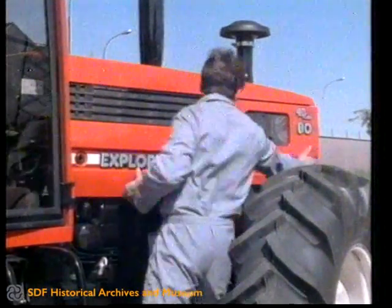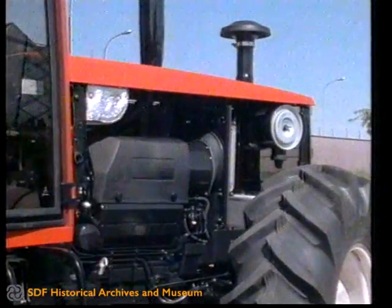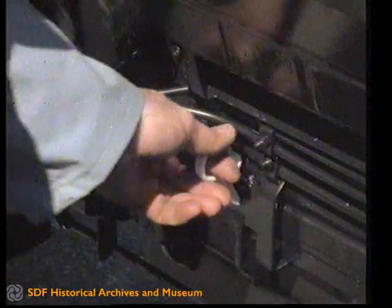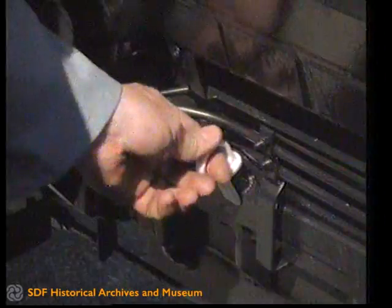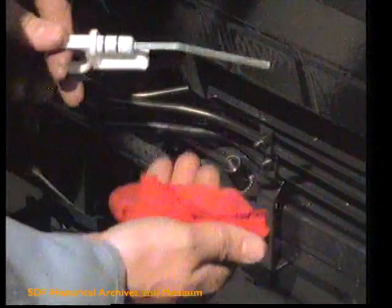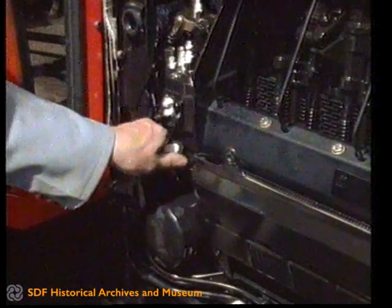In particular, the extremely rational design has meant that ordinary servicing can be carried out all from the right-hand side, where the dipstick, the filler pipe, the oil filter and drain, the lubrication circuit's thermostatic valve, the delivery and injection pumps, the regulator, the cooling fan, and the battery are located.